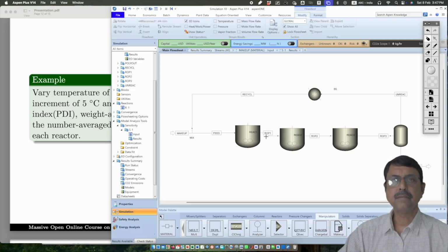That is understandable, right? Because no matter how you are changing over here, ultimately the feed is having the same rate of ethyl benzene, styrene, and all other things, along with the temperature and pressure. The same thing is going inside the reactor 1. So this is in the upstream of the reactor 2. You are changing the reactor 2 temperature, but nothing in the upstream should change, right?